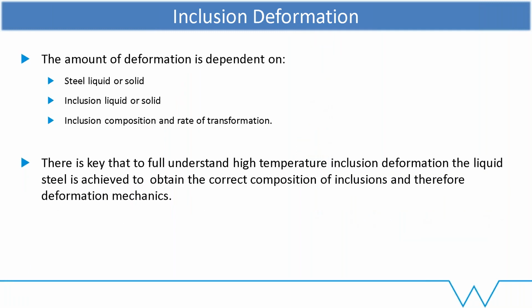Once we have that information, we can start getting a bit of information about the mechanical properties, and that's what the work that's going to be coming next is. Once we have an idea about how much it's squashed, then we know what the hardness should be, what the strength of that inclusion should be. If it deforms not very much in a solid matrix, then we know that it's got a much higher strength than the steel, and the steel preferentially deforms around it.